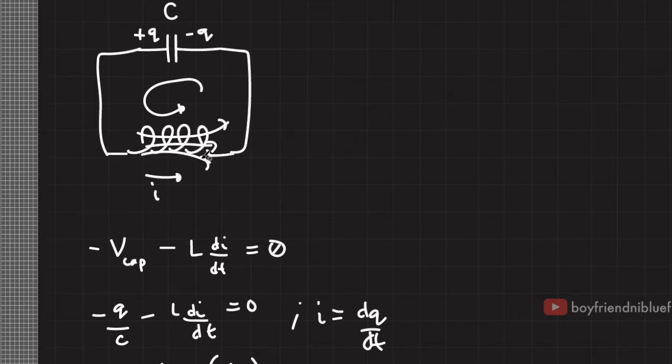And remember that when you have a fluctuating magnetic flux, since the current is changing over time, this produces a back EMF, and such EMF will resist or oppose the change in current. So by the time the capacitor is completely discharged and the current in this inductor is constant, the magnetic field will then produce an induced EMF, and this induced EMF will push the current in such a way it will continue charging the capacitor in the opposite direction.